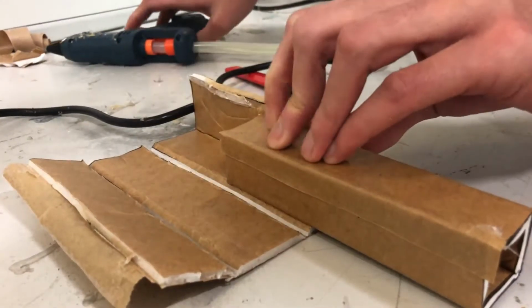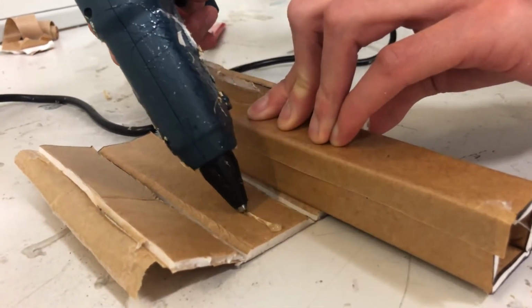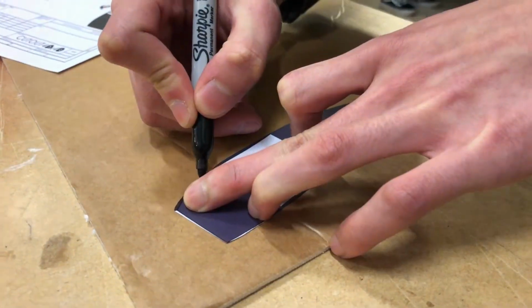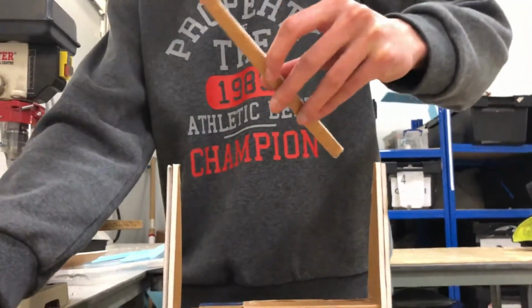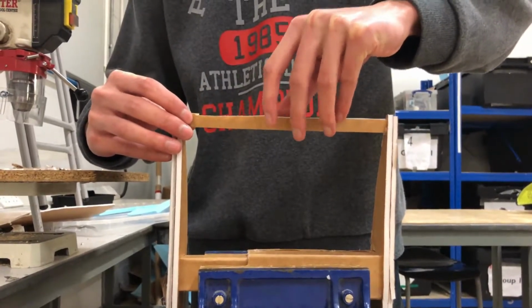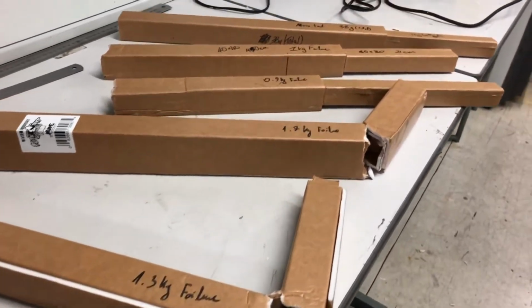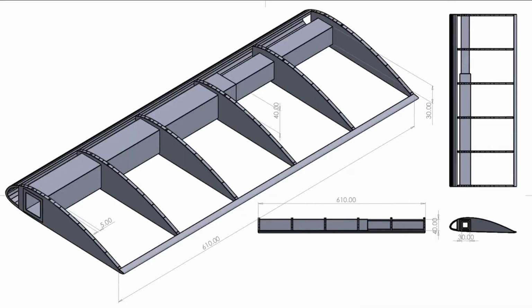spar. When it came to manufacturing, one must always remember that due to human errors and imperfections, the final product will always differ from the initially designed one. We, as engineers, need to work with exemplary precaution to minimize those errors by, for example, taking multiple measurements. Both Excel and SolidWorks predictions turned out to be imperfect, so we had to produce several spars and test them individually. In the end, we went for the presented design.